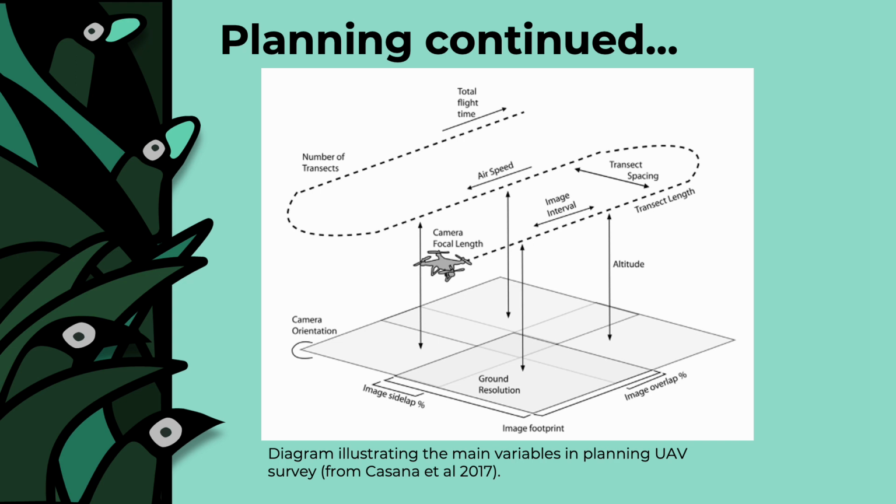For example, an area of about 1.5 hectares flown at an elevation of 40 meters and at a speed of 2.4 meters per second will collect about 260 images within a 15-minute flight on one battery. The resolution of such imagery will vary depending on the camera used. The 260 images in this example would require about 2.1 gigabytes on the micro SD card installed on the UAV. When mapping larger areas, semi-autonomous flight planning software can accommodate multi-battery operations.